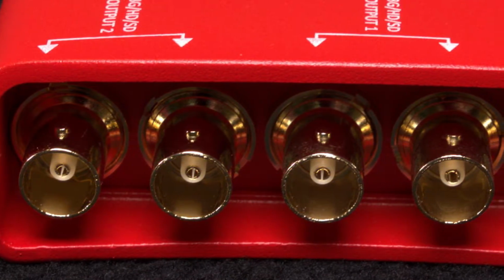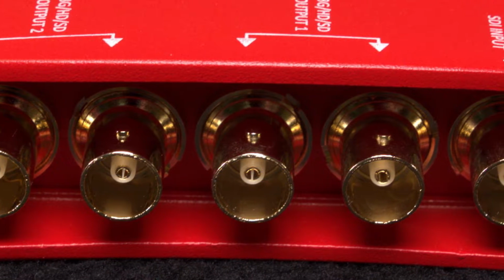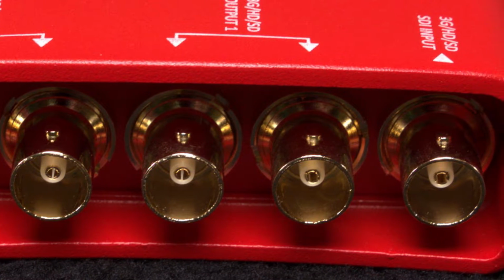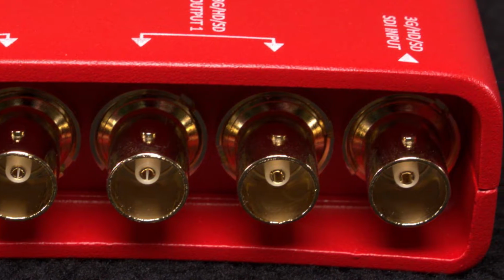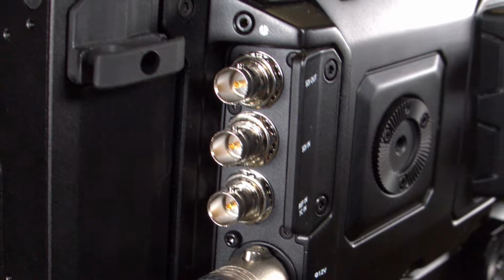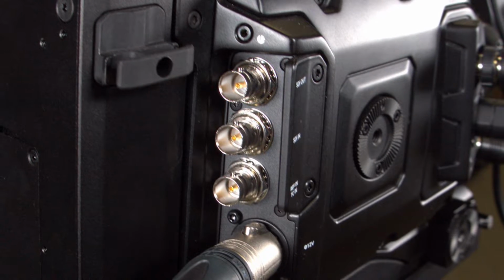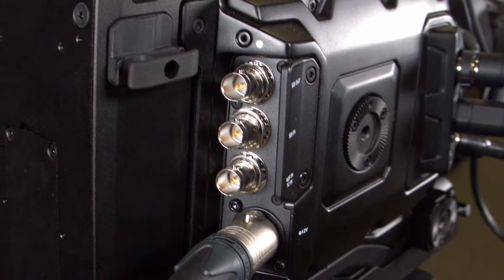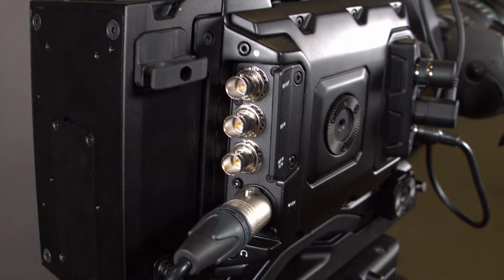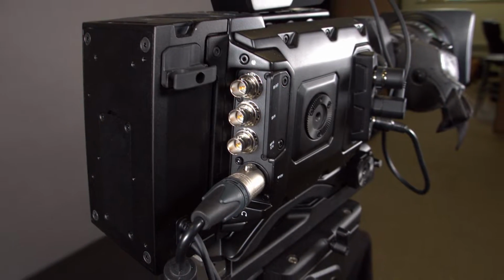SDI, or Serial Digital Interface, is a strictly professional standard for video transfer using coax and BNC connectors. It is far more flexible than consumer standards because it allows multiple channels of audio and video to be configured based on the specifications of the devices involved. Today, it's commonly categorized by the data transfer rates being used. Presently, the max is 12 gigabits per second, or 12G SDI. 24G SDI is currently under development.